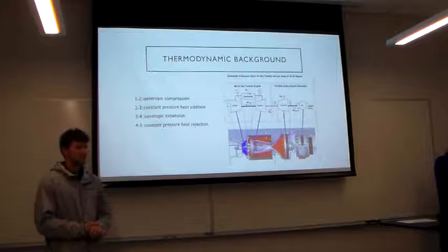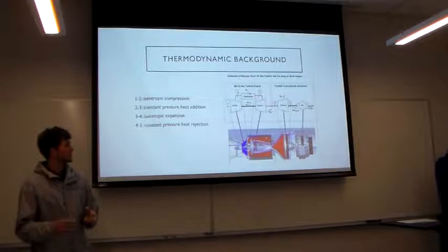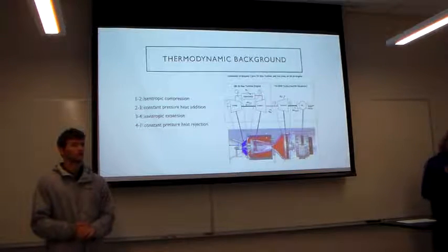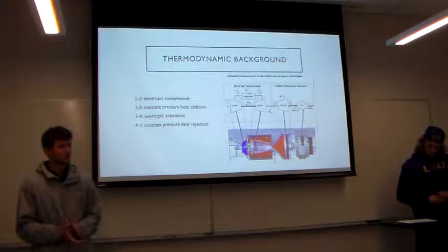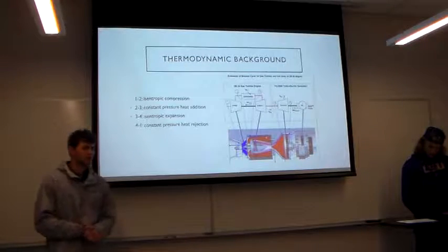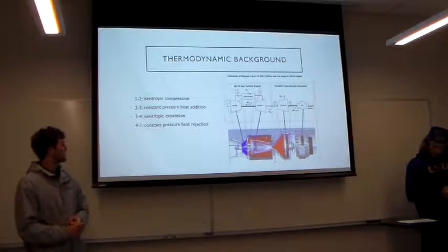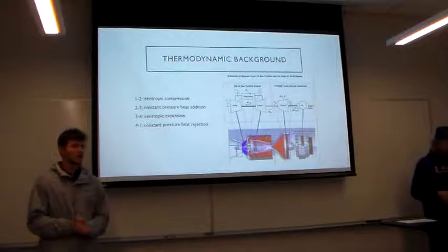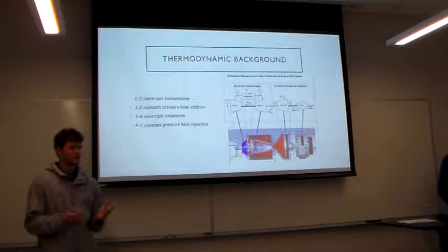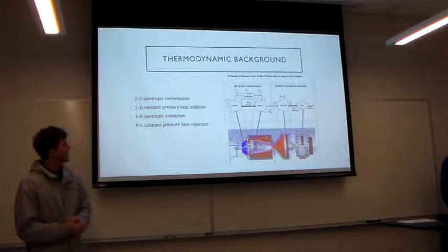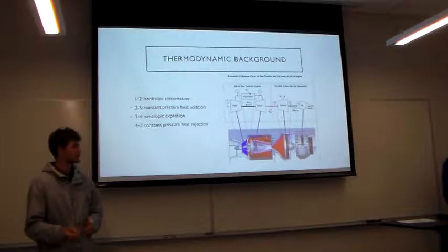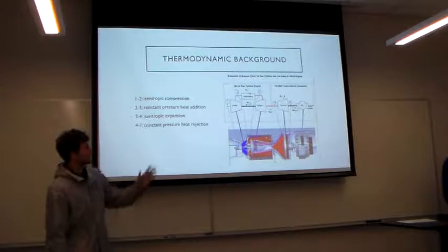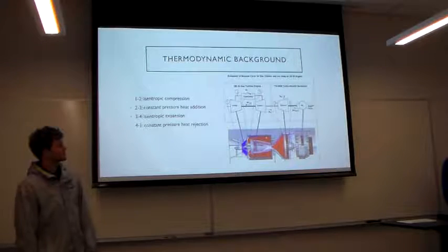All right, so like I mentioned before, compressor, combustion chamber, and turbine make up the gas turbine. And since the working fluid is air, it is called the Brayton cycle. What's going on here is a couple of isentropic processes and a couple at constant pressure. The compressor and the first turbine are the ones that, ideally speaking, are isentropic, and the combustion happens at a constant pressure, heat addition.